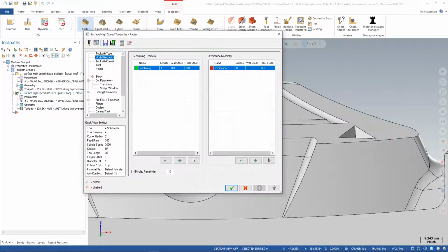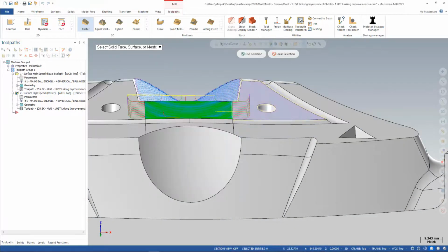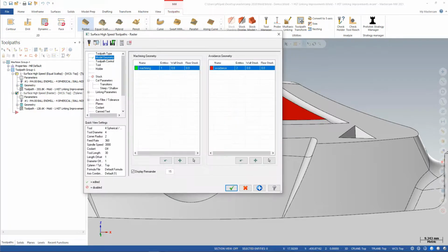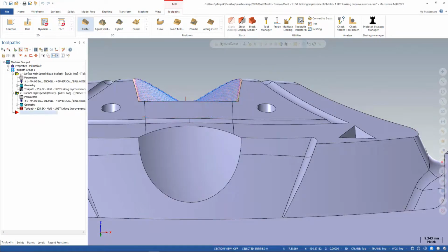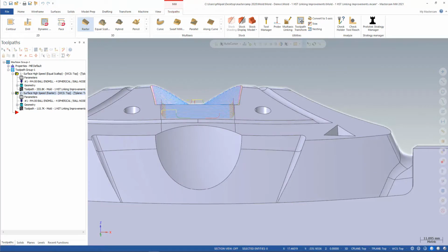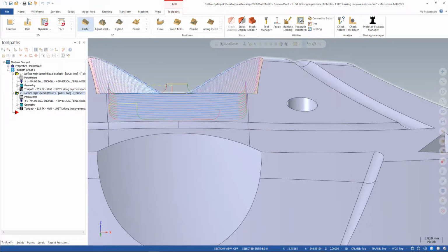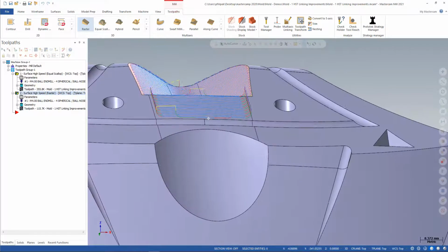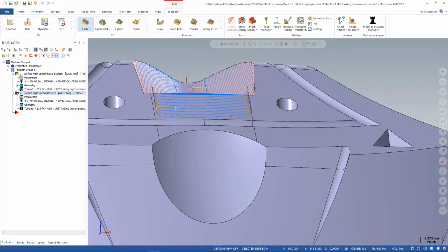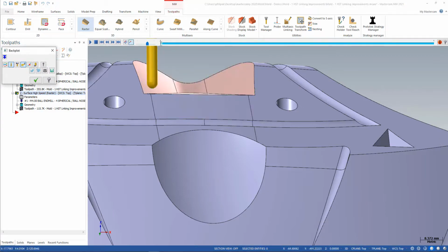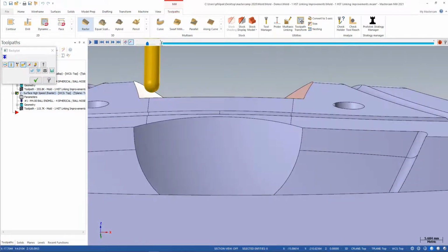If we go back and if I add these back as avoidance, like I had before, and if I put any value in here, let's just put 3 millimeters in there. Now if I regenerate the same cut, it does respect them surfaces. So if you have stock to leave on there, it's not going to gouge in even with the extensions. It knows better, so now it needed to cut that back so it didn't gouge into the surface since I left 3 millimeters on there.